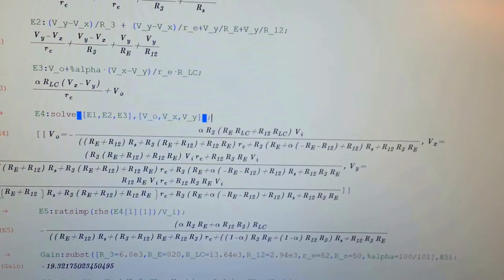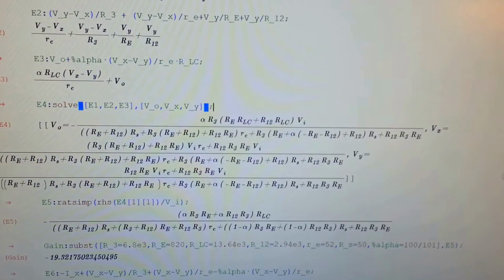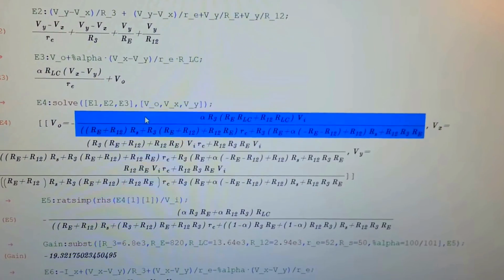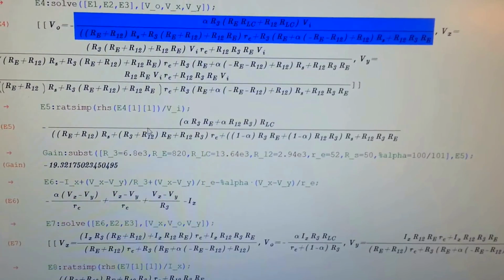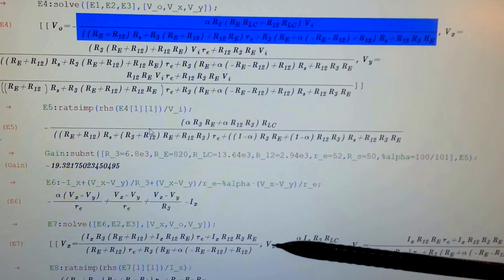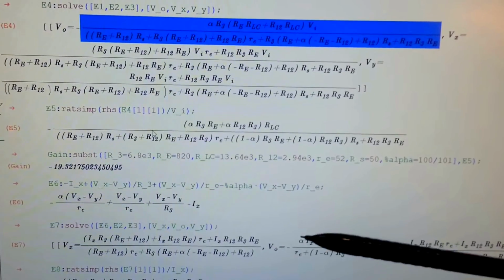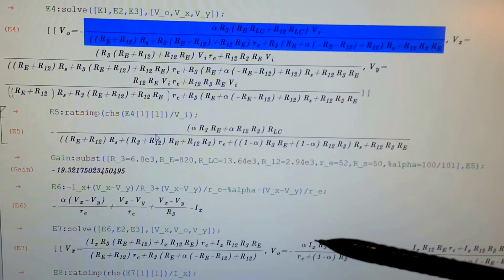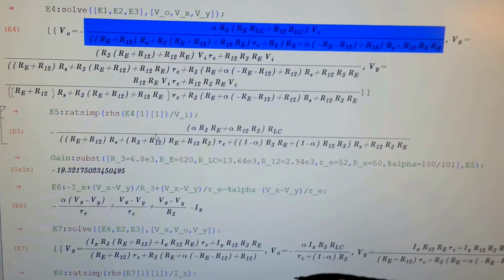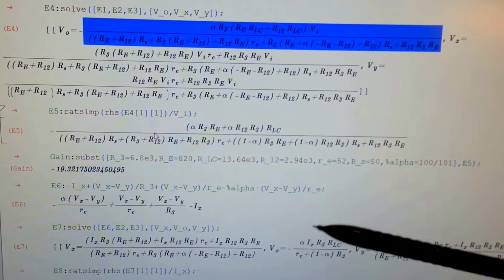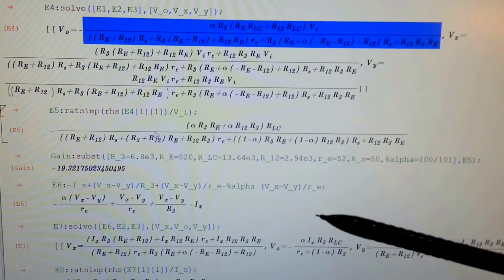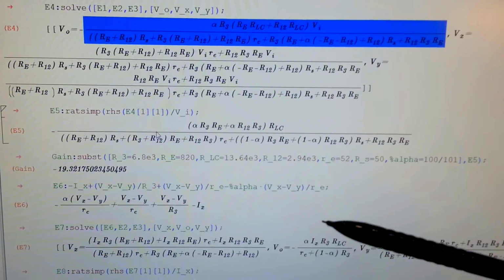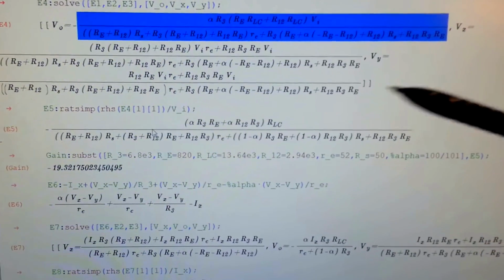And let's go ahead and do a computation for the input impedance. How much does the input impedance increase? Remember our input impedance from the previous video that we calculated for the non-bootstrapped common emitter amplifier was about 2.85 kilo ohms. We even measured that, which practically agreed spot on. So now, does this circuit, which includes the positive feedback network, help the input impedance? Let's take a look.